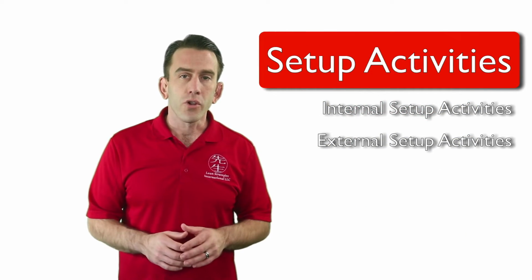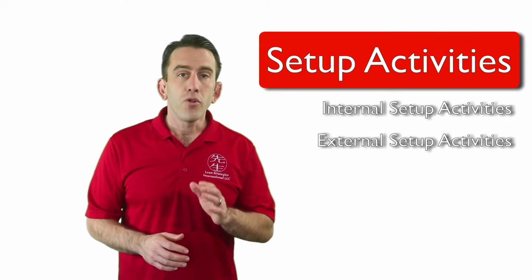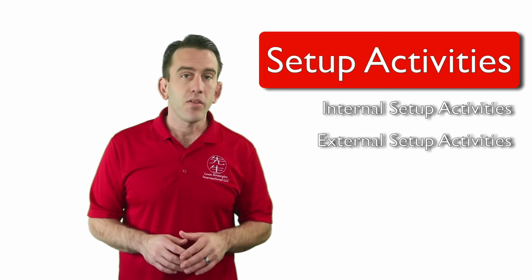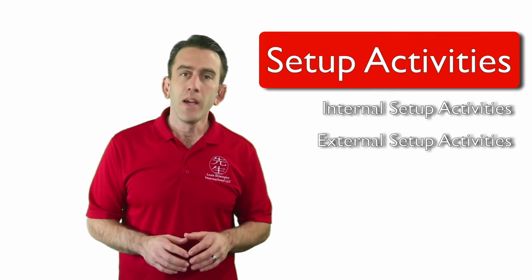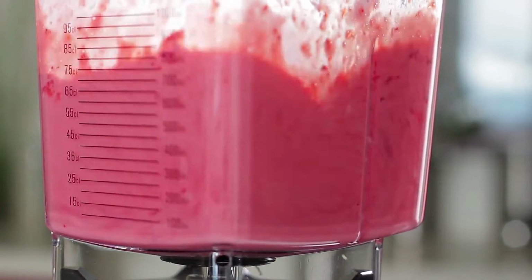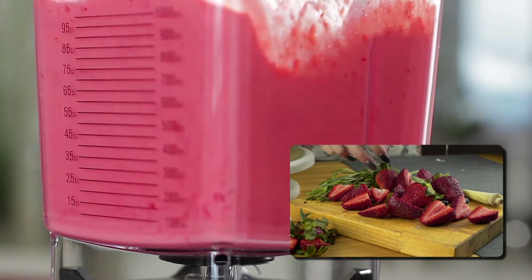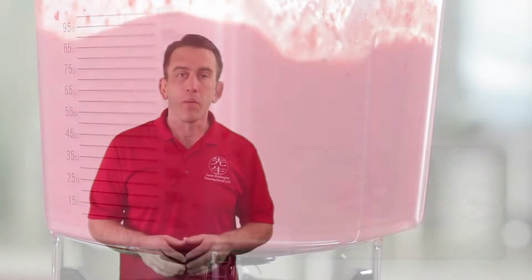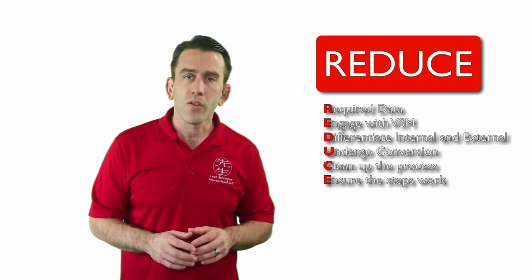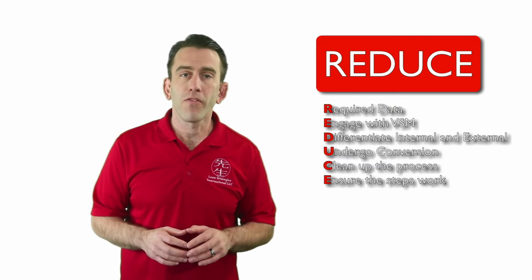Over the course of Dr. Shingo's career, he identified two main categories for setup operations: internal setup activities and external setup activities. He learned and later taught that many internal operations could actually be done externally. This dramatically improved changeover and setup times while allowing companies to run machines and create value for longer periods of time. The reduce methodology presents the main concepts of Dr. Shingo's SMED system in a more granular and simplified approach.